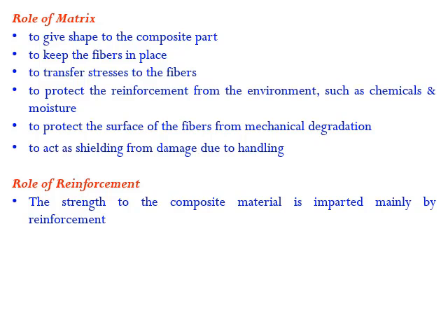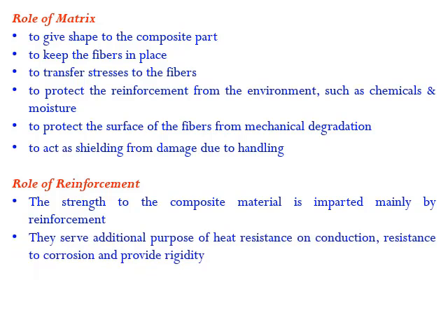So now what are the roles which we expect from the material which is inside the matrix? The first is the strength. The strength of the composite material is mainly from the reinforcement material. They serve additional purposes, like resistance to conduction, resistance to corrosion, and providing rigidity.